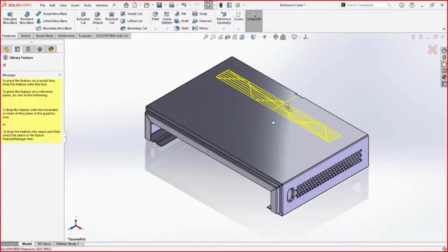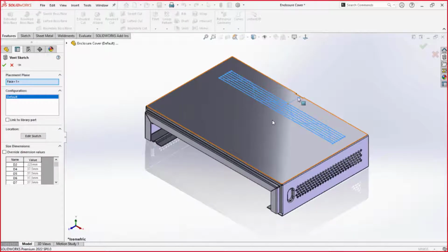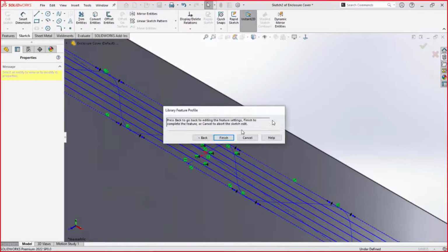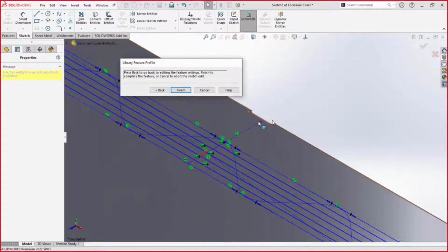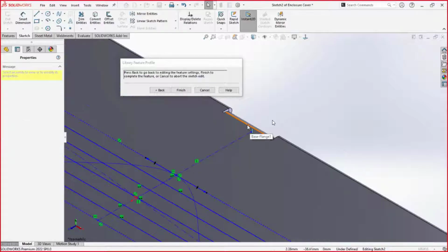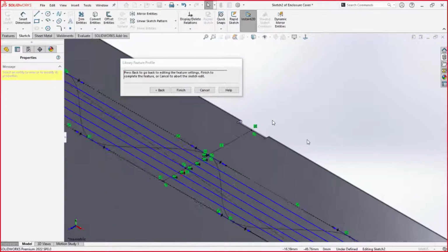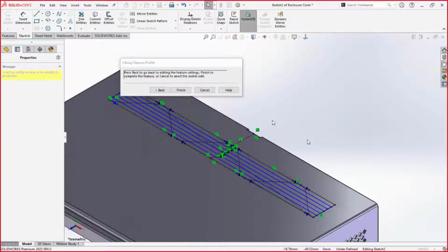Okay. So now again, I want to introduce the SolidWorks quick access tools and the snapping advantages. Let's say if you want to fully define this, you can edit the sketch like this, and you can leverage the quick access tools and hold the control key to make these two coincident. Don't need to go somewhere and make the changes. Simple. Once you're done with this, you can exit the workbench, and I'll use the vent tool.